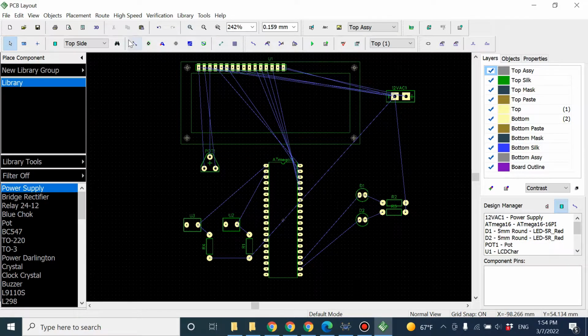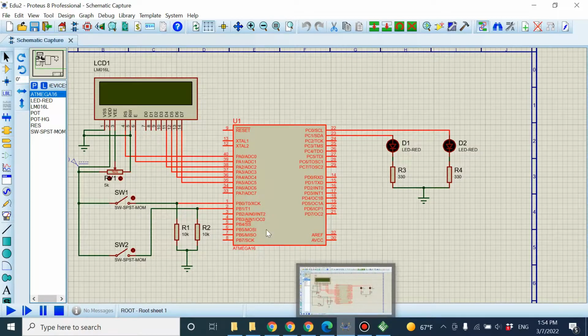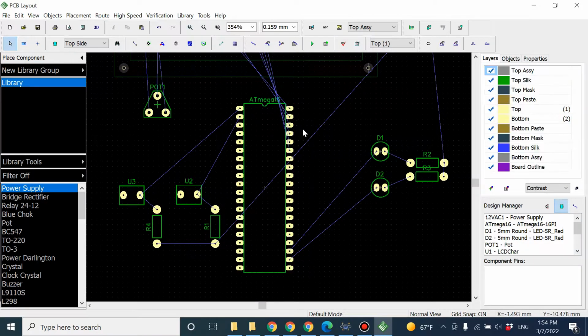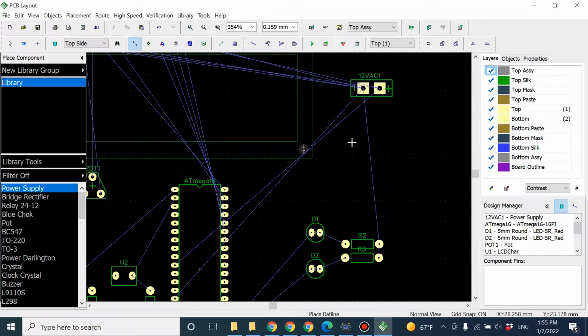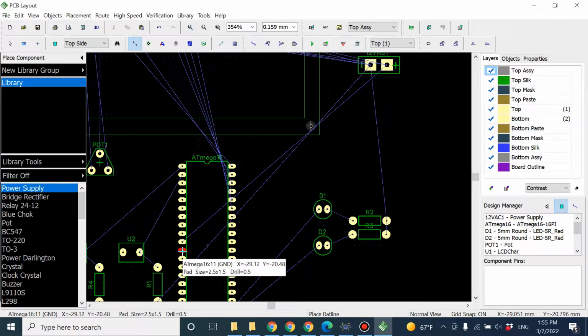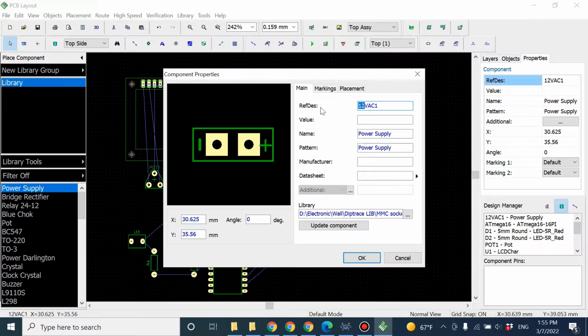Of course, remember in the simulation, there is no VCC or GND pin on the microcontroller or most ICs. But in a real PCB, you have to remember this one. This is pin 10. It's VCC. It goes to positive, and the GND goes to GND or negative. And you should know this system operates with 5-volt DC.